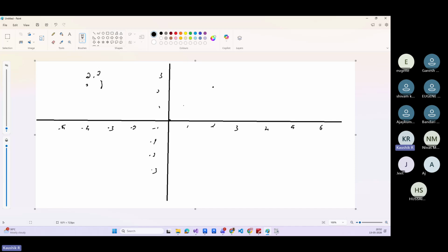How do you get the vector between 2 points? The formula is (x2 minus x1, y2 minus y1, z2 minus z1). How do you normalize the vector? A cap AB equals the AB vector divided by the modulus of the AB vector. And the modulus of the AB vector is the root of (x2 minus x1) the whole square plus (y2 minus y1) the whole square plus (z2 minus z1) the whole square. These are the mathematical concepts you have to understand to do any Revit API operations.